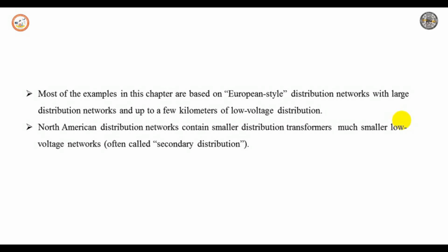To be technically correct, voltage fluctuation is an electromagnetic phenomenon, while flickering is undesirable, resulting from fluctuation of voltage in some loads. However, the two terms are often linked together in the standards, so we will also use the common term, voltage flicker, to describe such fluctuations.